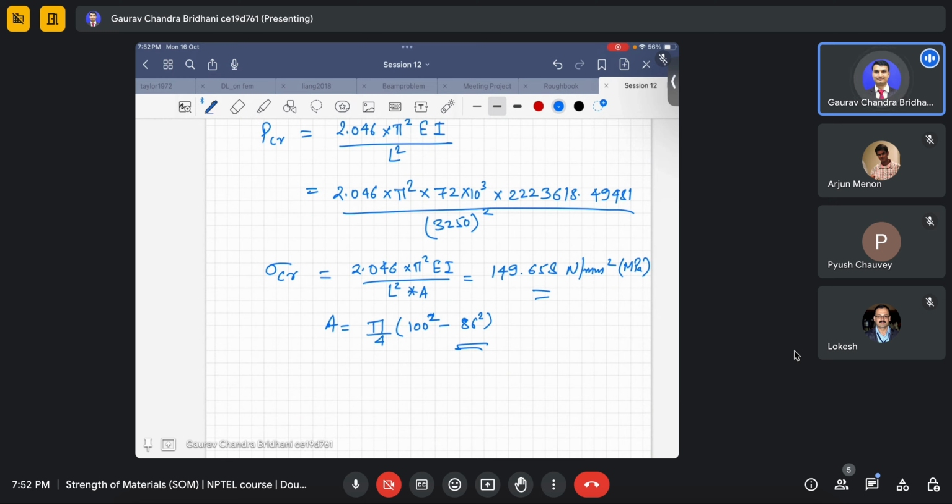Okay, and it's a thumb rule that it should always remain below half of the proportional limit. So we have 480, so I would say it should always be below 240 MPa for buckling, because, as I said, it's a stability issue. A very little perturbation of the system around the P critical value will cause a significant failure. Okay, it will cause a significant failure. So that's why it's a stability issue, and that is why this is a major concern in many constructions.